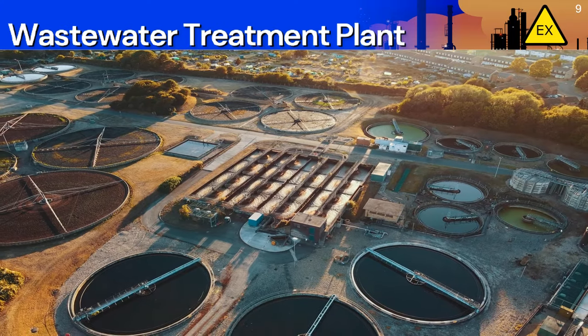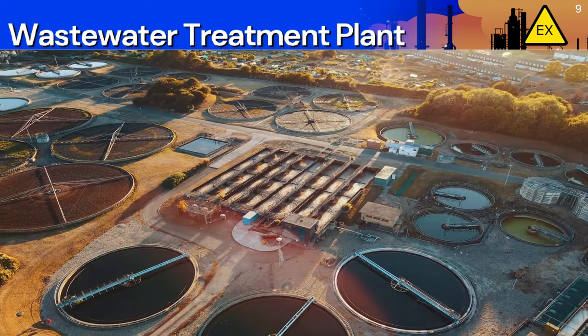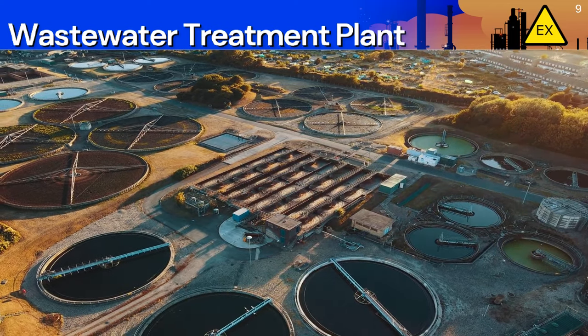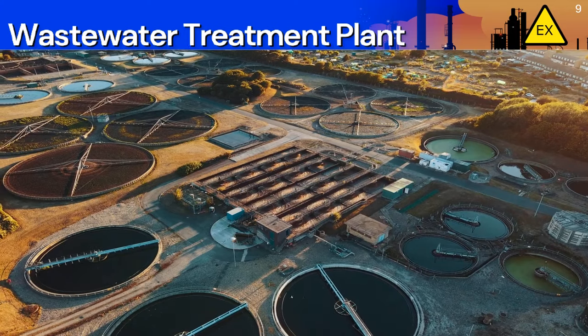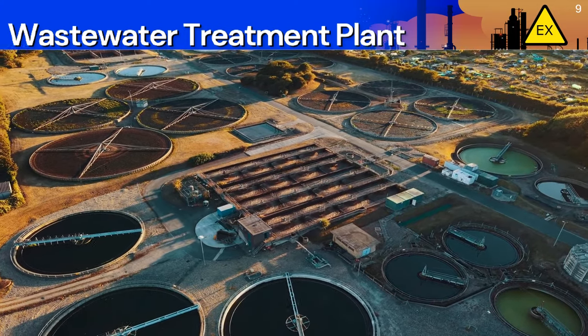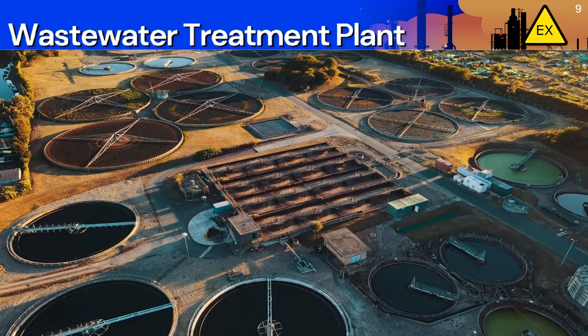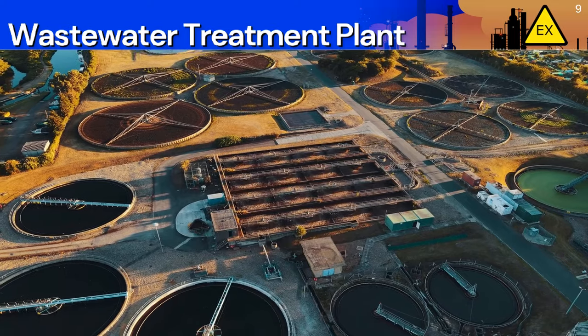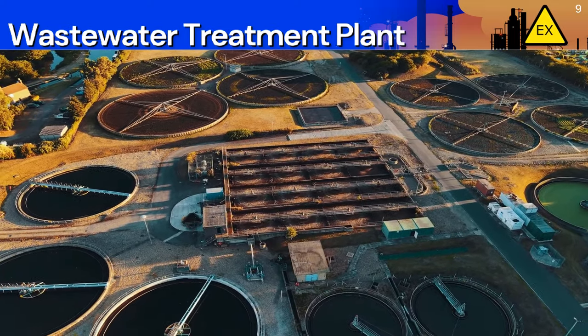Many biological processes can create a flammable atmosphere as a byproduct. Wastewater treatment plants are a great example. They produce large quantities of biogas from their anaerobic digestion of sewage. Biogas is explosive, and process equipment handling biogas will warrant a classification.